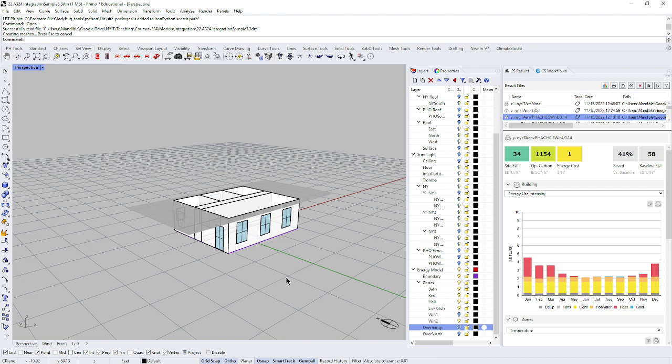EUI is energy use intensity. We have a baseline that's for typical buildings. Just think of a code building. For this type of building, this was a residential that would have different baseline EUIs than an office building. So we define that first. And then we sort of in a game try to get our site EUI well below the baseline EUI, because this is just a pretty lame number. We need to do much better than that.